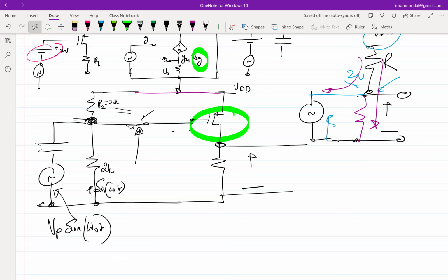Yeah, so the capacitor gets replaced with its phasor equivalent impedance, which is 1 by j omega naught c. So let me replace that. So this is 1 by j omega naught c. Again, what does this omega naught represent? Which frequency? Yeah, it's not necessarily the fundamental frequency, it's the frequency of the source. If the source has multiple frequencies, then the capacitor will also give you multiple impedances.